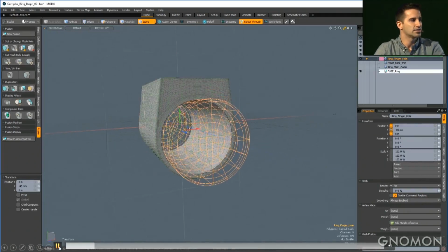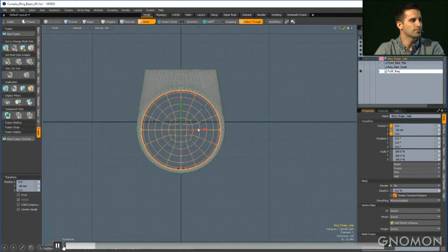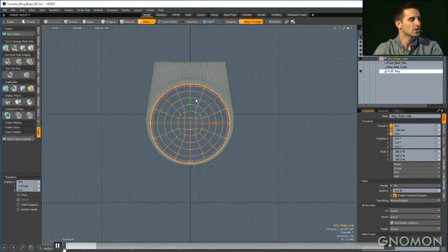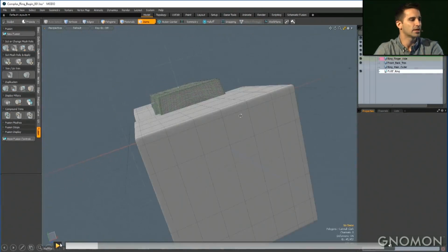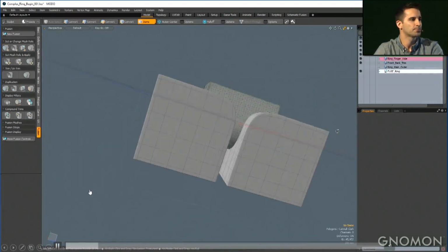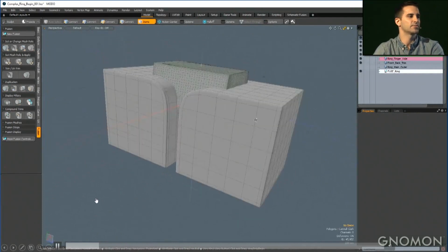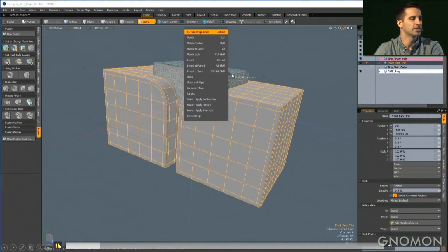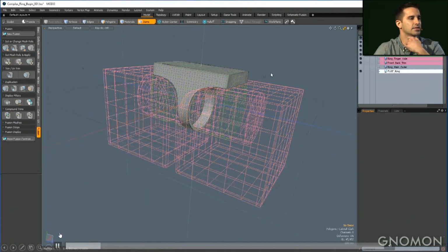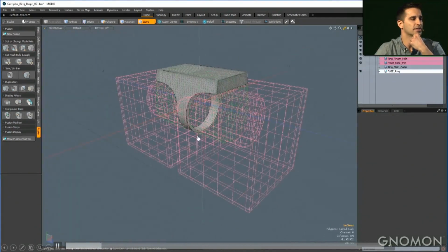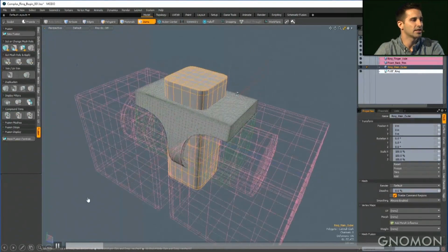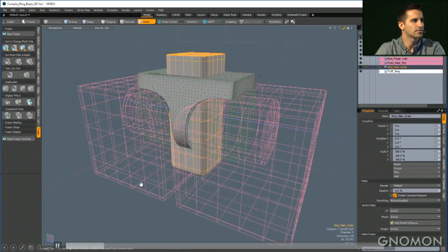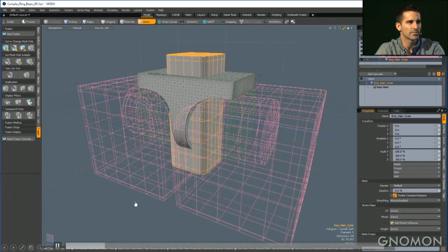And now I can just adjust the subtractive element. And you'll notice that the Fusion is only updating when I mouse up from the Move tool. And that's because deferred updates are activated. So I'm also subtracting this pair of cubes, so they also get the magenta wireframe. And now this tall block is going to be, let's see, a mesh operation. It's going to be a trim as well.